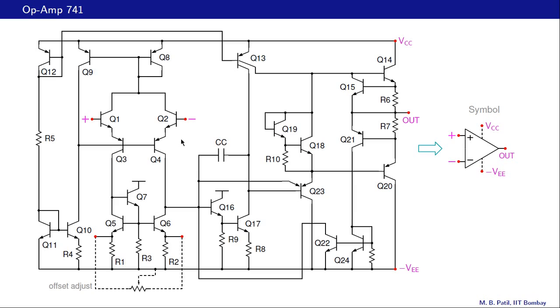Now that is not what happens in real life. In reality the transistors would be close but not quite identical, and there would be small differences between the two, and therefore it gives rise to the offset voltage. That means the VO versus VI curve gets shifted, as we have seen in the last slide.